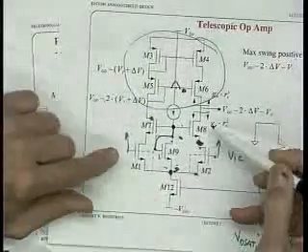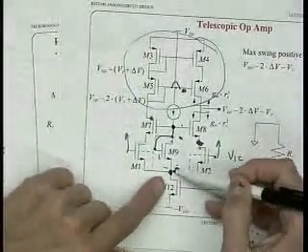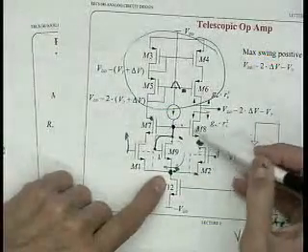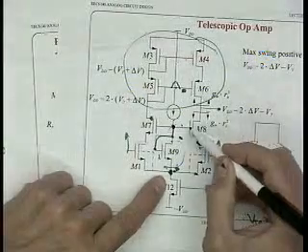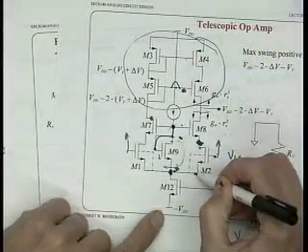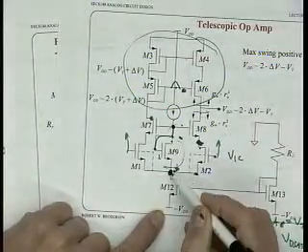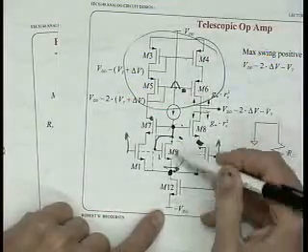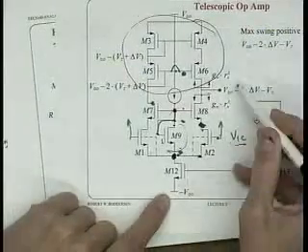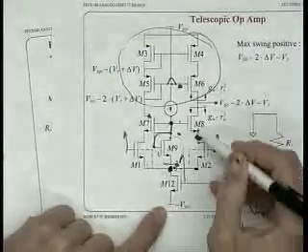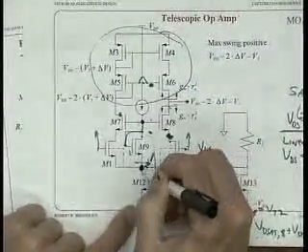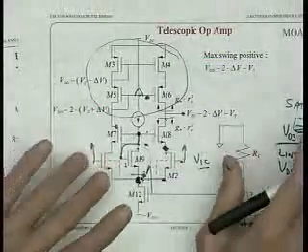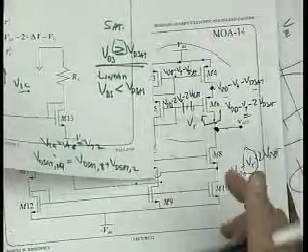This circuit, even if we try to, this is actually a high swing. M9 sets this M2 into a high swing condition. We're 2 VDSATs from here to here. Unfortunately, we've got this voltage which goes up and down with V input common, so what really kills our swing in the negative direction is the fact that when this goes up, this voltage goes up, even though it's 2 VDSATs to this point, but this voltage is getting fairly high, right? And that's really bad. So that's what this one gets rid of, that problem right there.